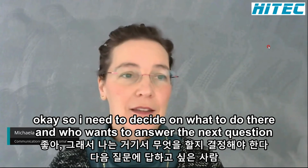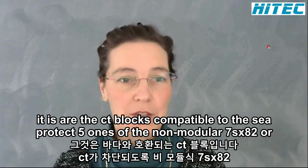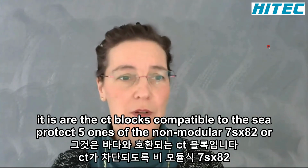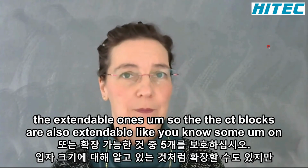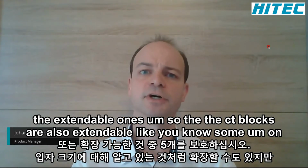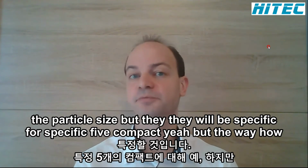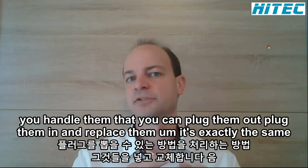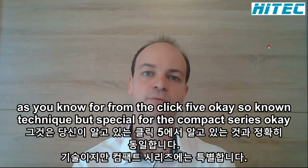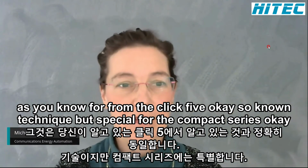Mm-hmm. And who wants to answer the next question? It is, are the CT blocks compatible to the SIPROTEC 5 ones of the non-modular 7SX800 or the extendable ones? So the CT blocks are also extendable, like you know from SIPROTEC 5, but they will be specific for SIPROTEC 5 Compact. But the way how you handle them, that you can plug them out, plug them in, and replace them, it's exactly the same as you know from SIPROTEC 5. Okay, so known technique, but special for the compact series.